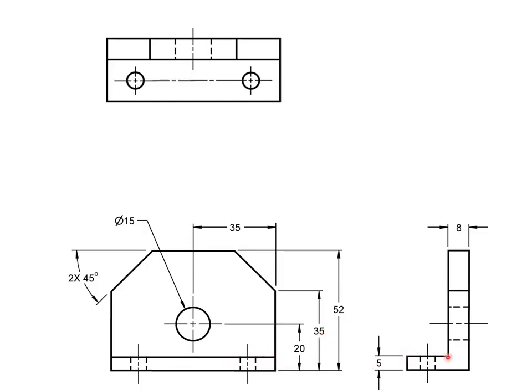But here we can see it's a step, so it's better to leave it on the right side view even though it's by itself. We also have this wall thickness of 8, so we're dimensioning from back to front, and we're missing the overall depth, so we'll show it in the top view. But before we go to the top view, let's take a look at the front.